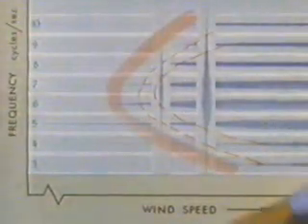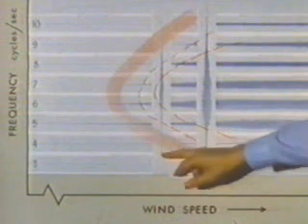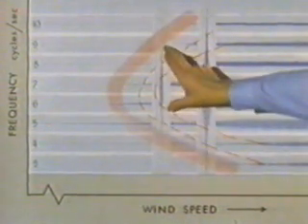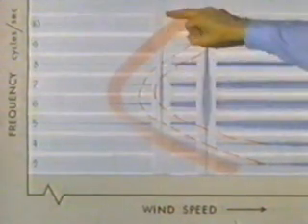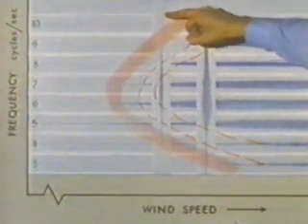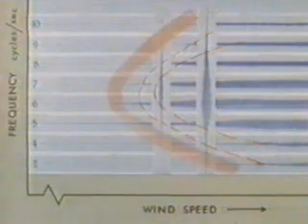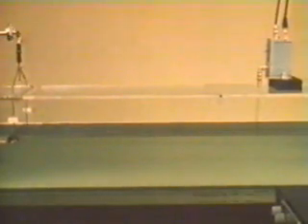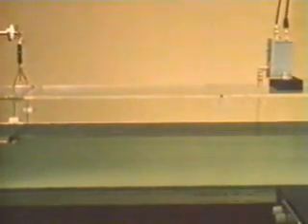So we see that at a given airspeed, the lowest frequency waves will not feel enough relative wind to grow. An intermediate range will grow, and the very shortest high-frequency waves will again be damped. This particular instability is rather complicated and involves many flow parameters: Froude number, Weber number, Reynolds number, water depth measured in wavelengths, etc., etc.